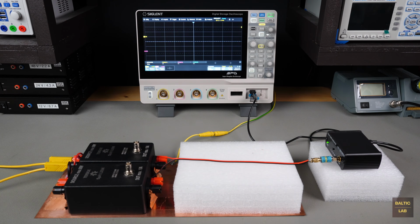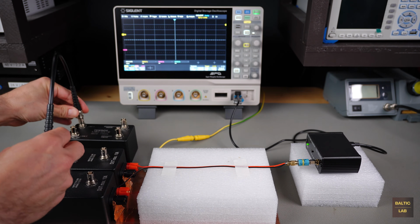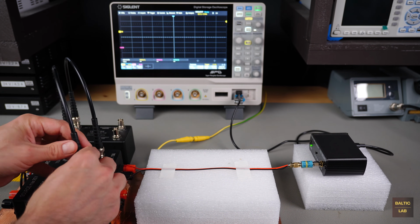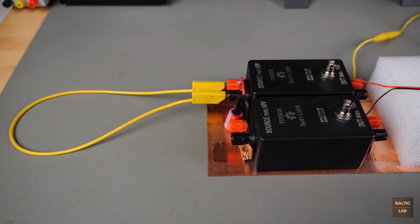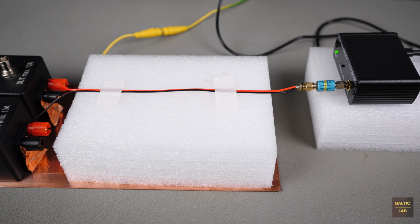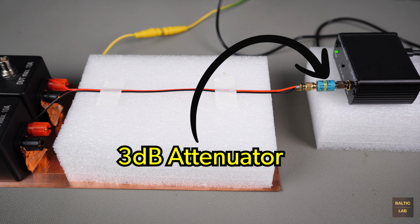The first test setup consists of two DC LISNs based on a typical CISPR 25 test configuration. These LISNs are connected to a TechBox LISNMate, which allows for separate measurement of differential and common mode noise. On the input side, the LISNs are connected directly to the reference ground plane using low impedance connections. On the equipment under test side, the LISNs are connected to a standard 2-conductor power cable, which in turn connects to a broadband noise source through a 3 dB attenuator.